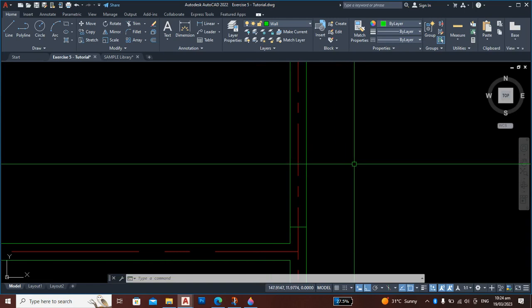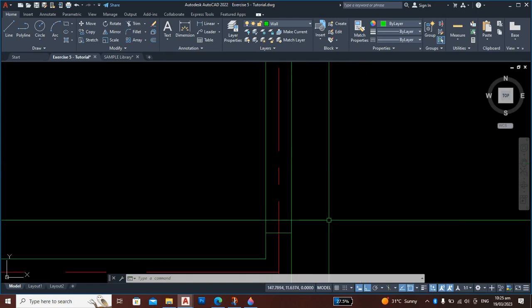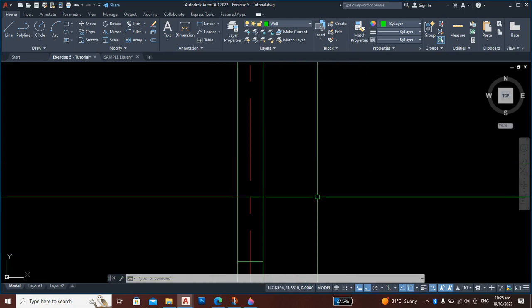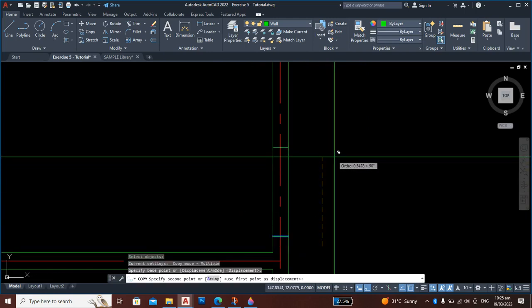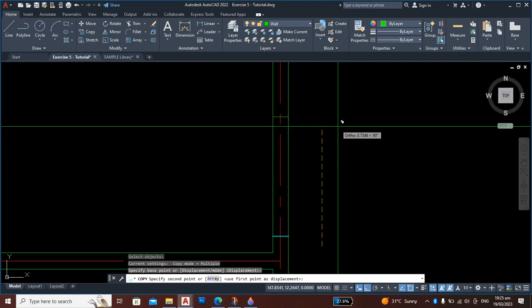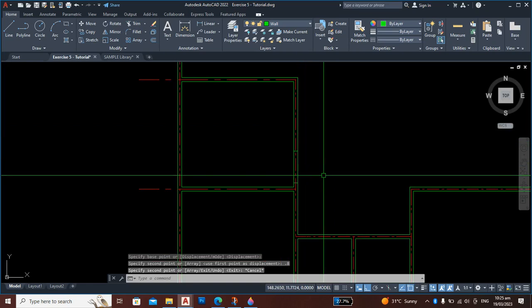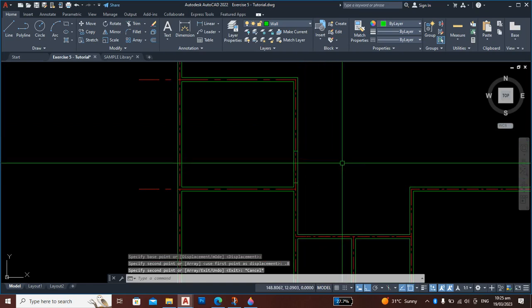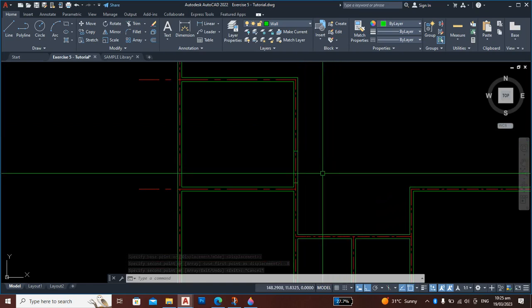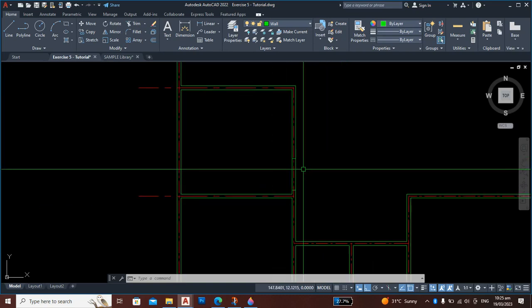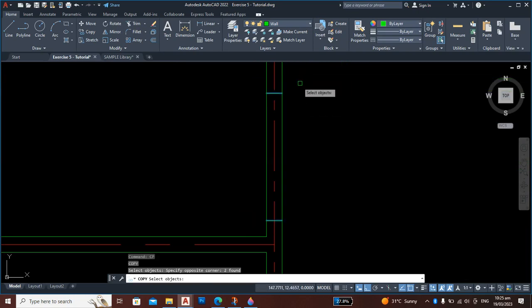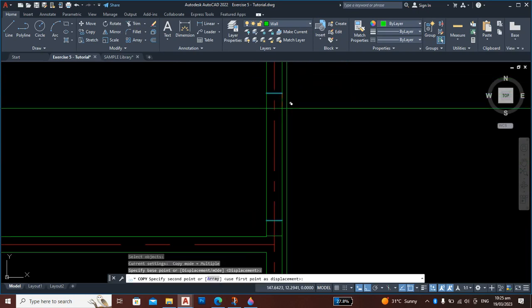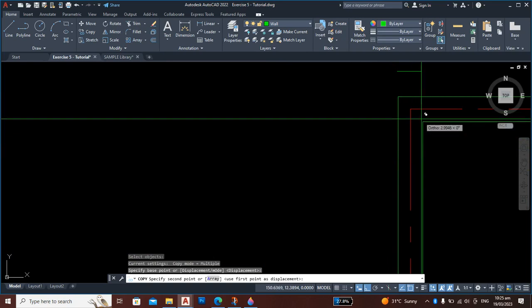So there are several commands to use here. You can copy or you can offset. So let's say I will just use copy and drag going up. Then type 0.8. Okay, since we have two doors, so that you will save time, just copy again these lines that you drew and put here.